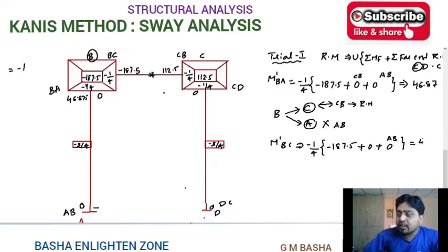Sometimes you will get symmetrical values only. Why? Because here the loading condition is point load only, and there will be no loads acting on the columns. So immediately take down here 46.875. Then come to the C.